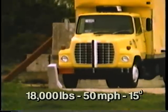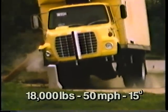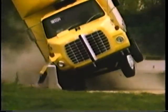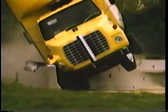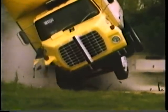In the 18,000-pound truck test, the front of the vehicle rode up the face of the barrier and rolled 31 degrees until the cargo deck struck the top of the barrier. The F-shaped barrier performed better than the New Jersey shape in this truck test, since the vehicle did not roll as much and was redirected without rolling over.